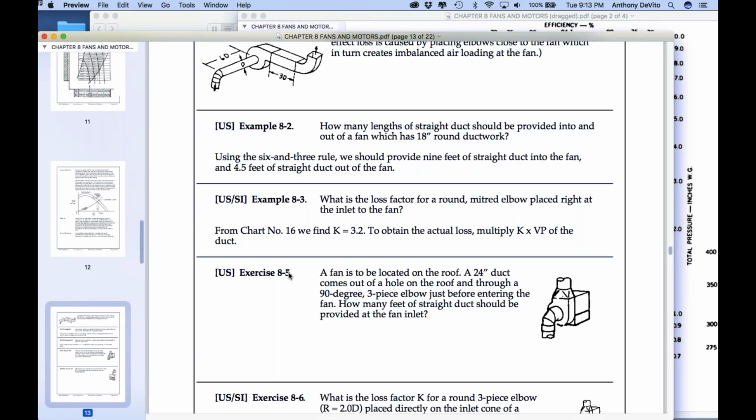You say to yourself, gee, it really would be better if they reduced the dust load to protect themselves a little bit better. But that's not really how they work. They use a fan designed specifically for keeping it under negative pressure, and that's for containment, to keep it from getting out of the space, not for removing the contaminant from the air. In fact, it's a HEPA filter, right? Because you don't want it discharging somewhere. Remove asbestos from your basement? Not asbestos. No. Concrete, from the client's site.